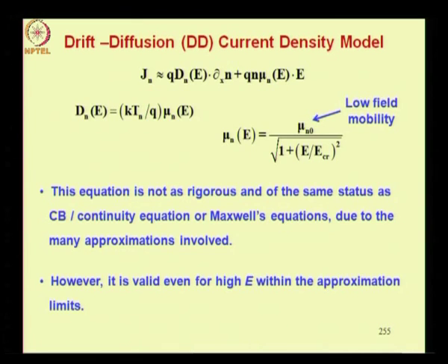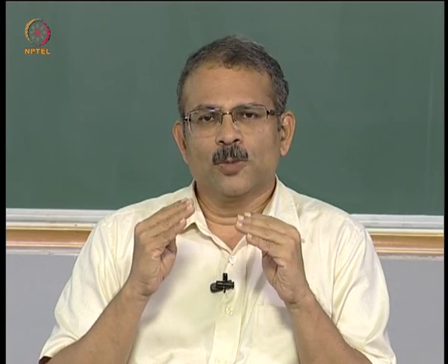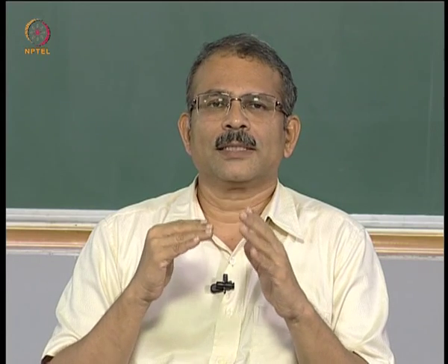However, there is a silver lining: the drift diffusion model is valid even for high electric field within the approximation limits. So, we need not assume that the drift diffusion model works only for the small electric field regime where the drift velocity is linearly related to the electric field.